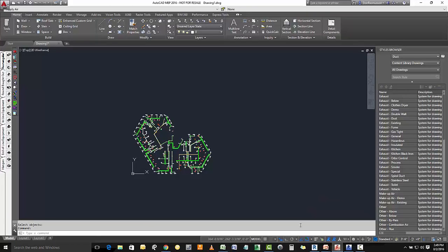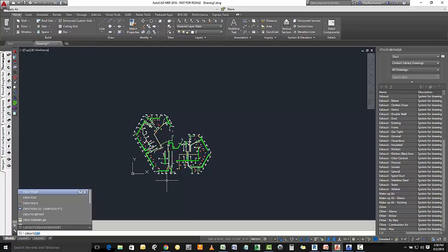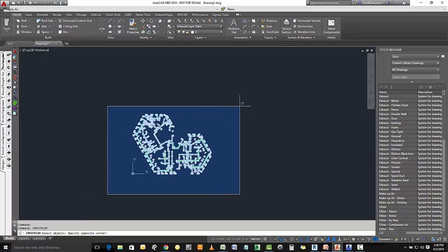So now let's go ahead and cover the Fabrication MAJ export and bringing that into Revit to provide that .rvt file extension deliverable that a lot of people are asking for. Here I am inside of Fabrication CADmep, and Create CAM is the command that we want to run. So I'll go ahead and run that command. I'll do a group select of everything.